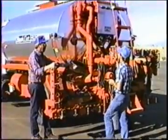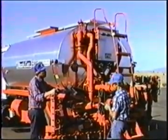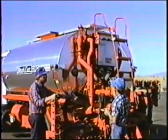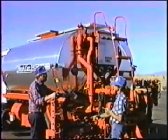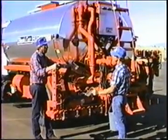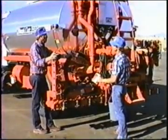Yeah, what we're going to do is, on the manual, we've already got this all figured out. Number 3 nozzle is going to spray at 8 pounds of pressure. You're going to set that regulator at 8 pounds of pressure. You're going to lengthen the bar, and it'll catch up. Exactly right. And lengthening is just one notch more complicated.